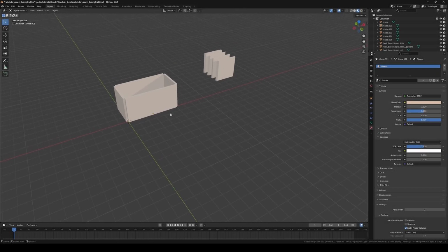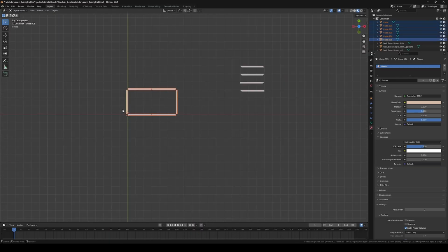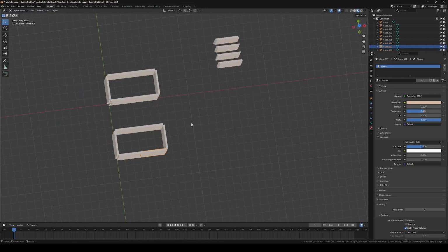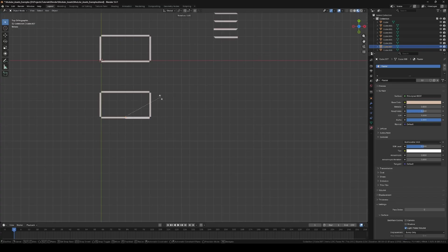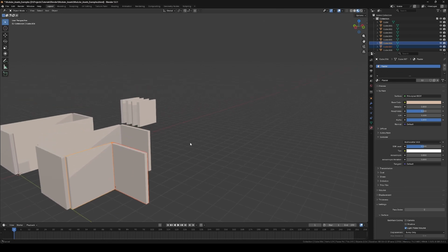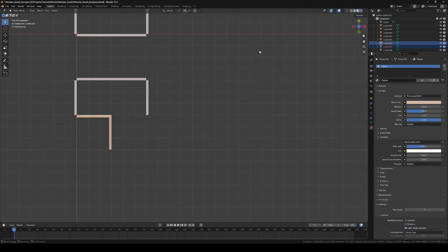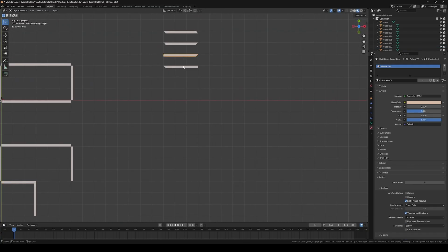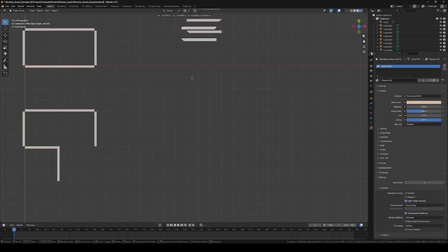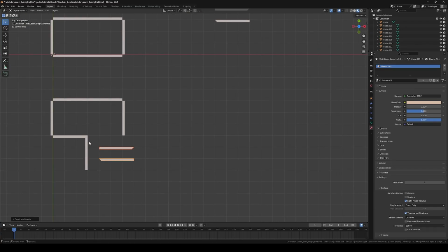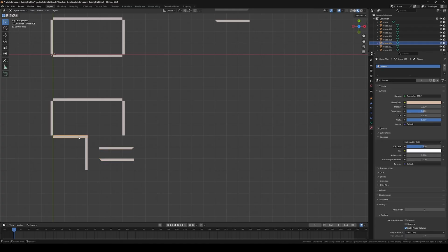There will be situations where you want a wall to move at right angles, but there's a possibility that you could get an overlap in the meshes. So to illustrate this, we duplicate our building and then we rotate by 90 degrees, minus 90 degrees, and now when we look at these two walls, we'll see that there is an issue with them overlapping. We can get around this if we make some other pieces where the ends, either one or both, have been moved so that they are sloped, which means that they no longer overlap with each other.